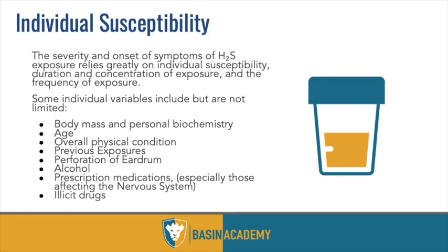So just a little fact out there, 10 parts per million is the industry permissible exposure limit, meaning you can be around 10 parts per million for 8 hours a day. But they've done studies about people who've been around 10 parts per million for 8 hours a day for 30 years, let's say, right? And these are people that work in the smelting, typically, or some sort of mining or metal processing, right? Guys that have worked around that. They're within the range, but over 30 years, the statistics, as you can probably imagine, are not great. People get sick. People get really sick. A lot of different health issues. So even though 10 parts per million is probably not going to affect you, boom, right now, it's going to be more of a chronic effect than an acute effect. It can have a lot of chronic effects, and that's what research and studies are showing us right now.